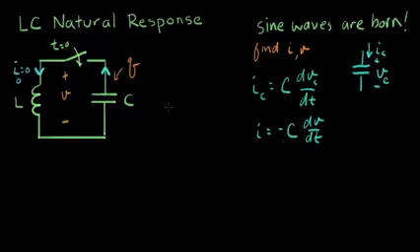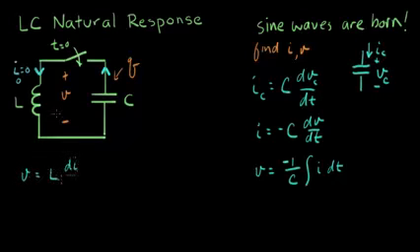And now I want to write the integral form of the capacitor IV equation, which is V equals 1 over C times the integral of I dt. And remember our minus sign. This is the important minus sign to bring along. Okay, so let's do the voltage across the inductor. The inductor voltage, same variable V, is L di/dt. So there's no extra minus sign here. This is assigned according to the sign convention for passive components.